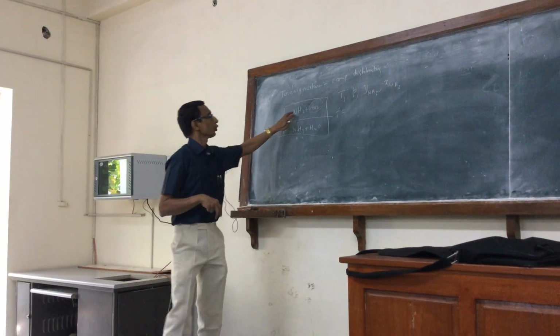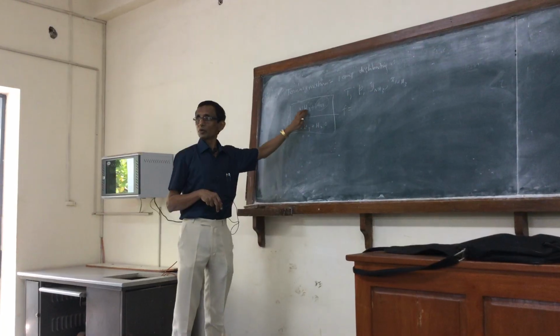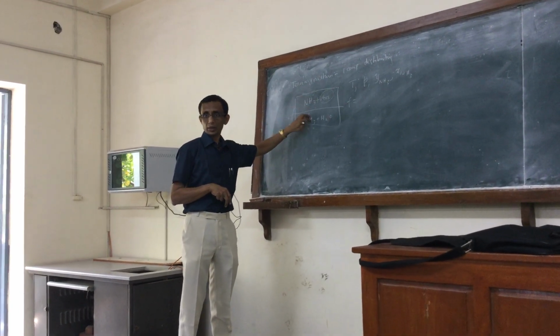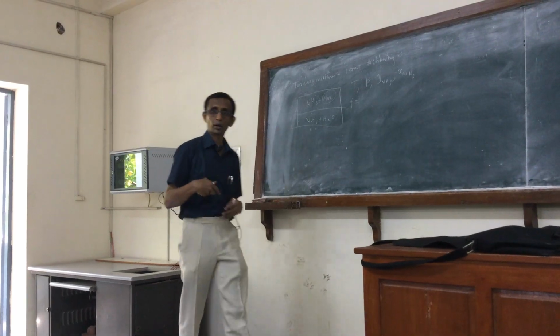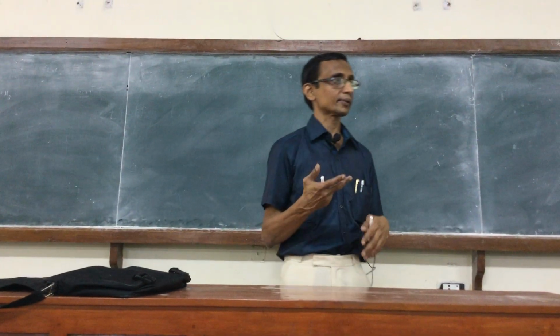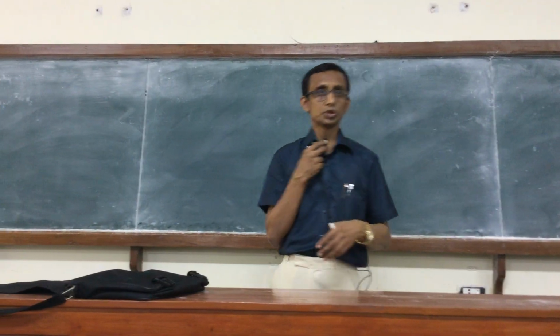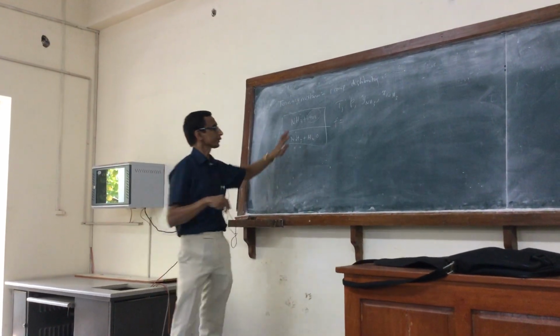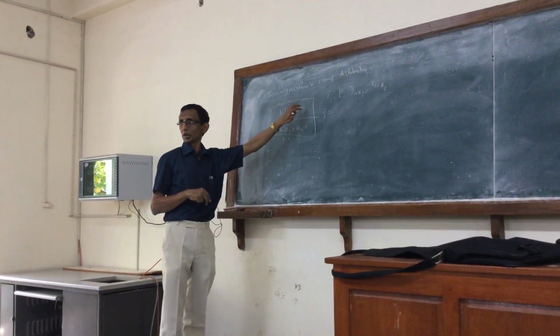So obviously our choice of the solvent would also be, a better solvent is one with which we absorb only the ammonia or carbon dioxide which we want to be removed from the gases. The rest of the things, we choose a solvent so that they are relatively insoluble. Now we are considering an extreme case where they are pretty much insoluble.